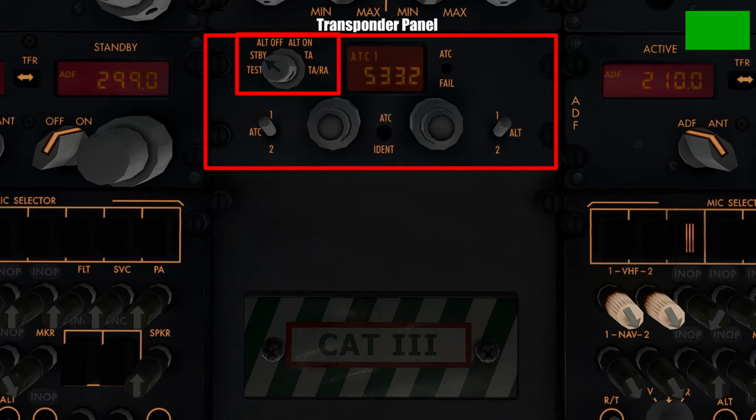This knob over here is the TCAS system, which stands for the Traffic Collision Avoidance System, which sounds little audible alarms in the cockpit when the transponders of two aircraft detect that they're getting too close to each other, thereby breaching safety regulations. The knob itself allows pilots to switch between the different modes offered by the transponder. When switched to standby, the transponder system is running but not actively sending out any information to air traffic control or any other aircraft in the vicinity.